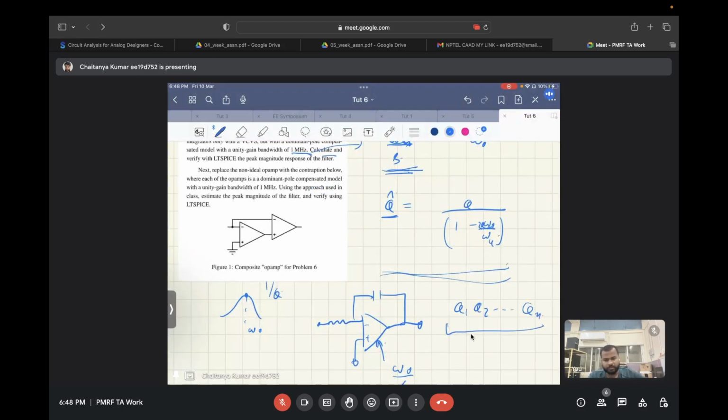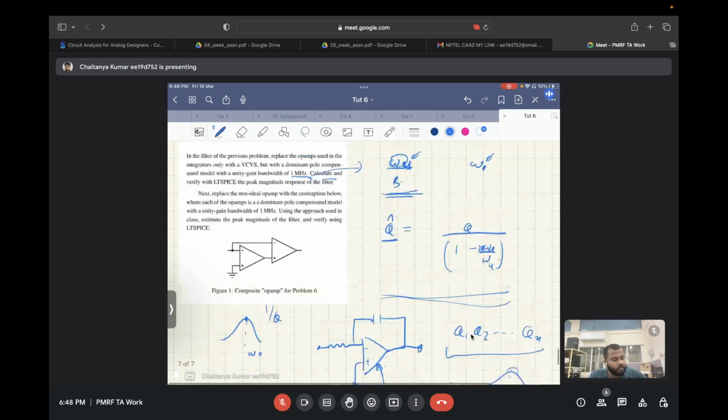This won't be the exact peak response, which will be somewhere different, but it is an approximation. As in the first case, you will see a peaking in the overall magnitude response due to the finite bandwidth effect.